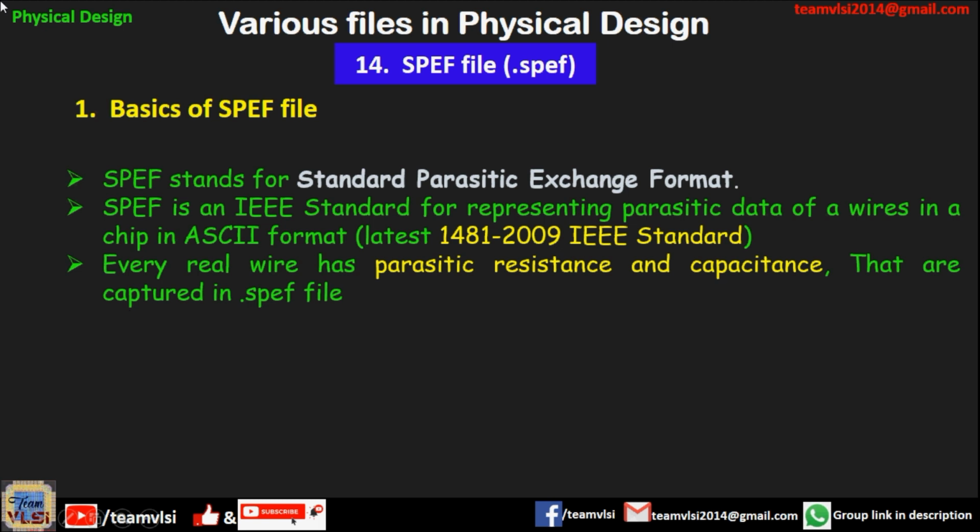Every real wire has parasitic resistance and capacitance that are captured in the SPEF file. So in your design, every interconnect has some parasitic resistance and capacitance value that will be extracted and captured in your SPEF file.